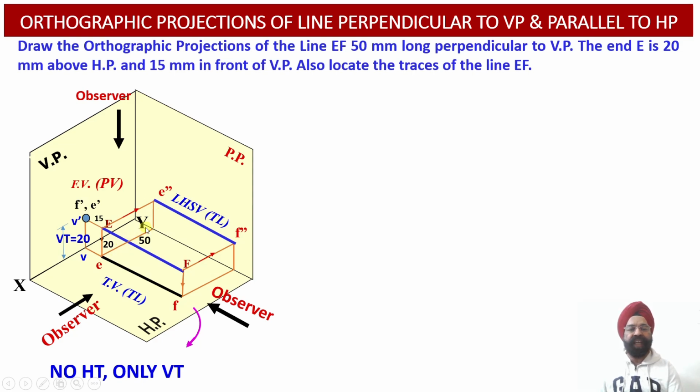Once we draw this projection line and this projection line, the relationship between E double dash and point E will be established. Similarly, draw one perpendicular line from here, and draw another construction line over here from point F. Once we draw these two construction lines, we obtain the relationship between F double dash and point F.